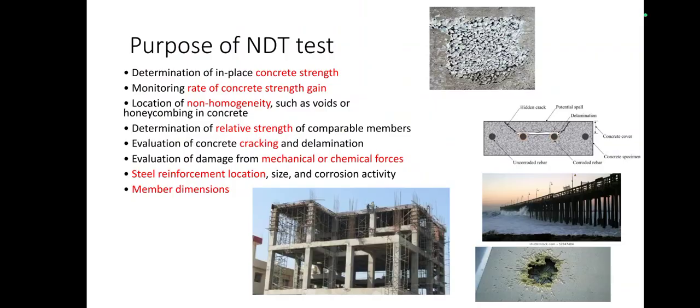If I cast cubes for that, consider 3 cubes at least for the first day, 3 cubes for the third day, 3 for the seventh day, 3 for the 14th day, and 3 for the 28th day. So almost 15 cubes you have to cast to identify its strength at the different days. Instead of that, if we do non-destructive testing, without wasting concrete, in an economical way, we can find out the strength gain.